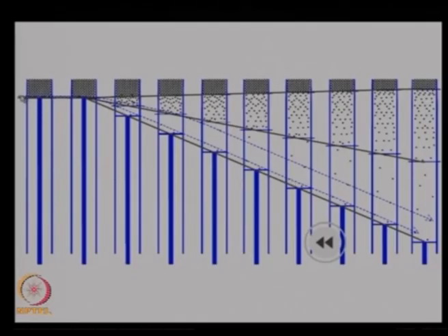If you are tracking that particle, that is the lower streamline, it is coming here, and it starts to turn somewhere around here where the first expansion line touches it. After that it changes and then it comes to a constant rate. After that it is moving parallel to the wall.